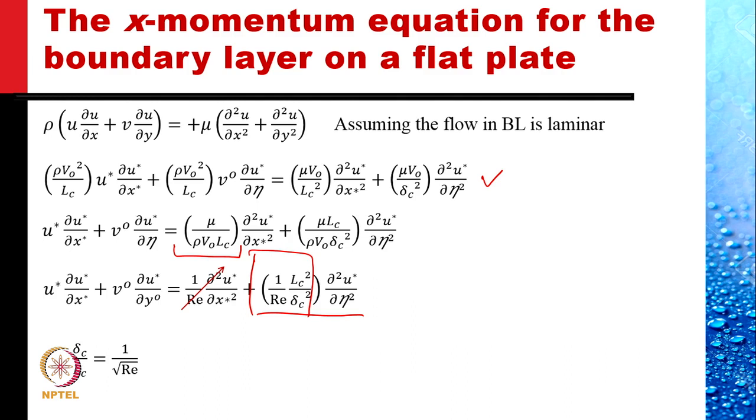With very minimal analysis, we have been able to obtain this estimate. We can do elaborate solving of these equations, and then we find the boundary layer thickness is about 4.5 divided by square root of Reynolds number. Same order.